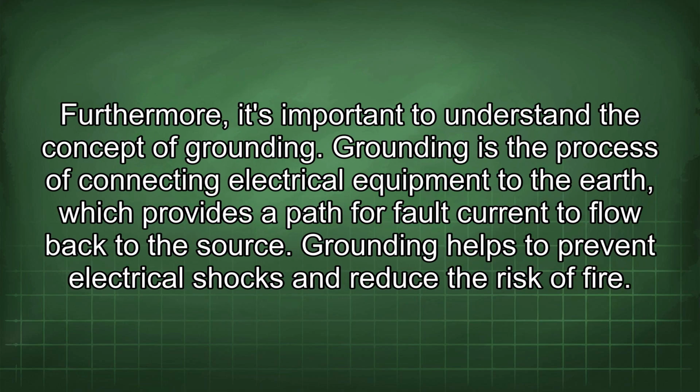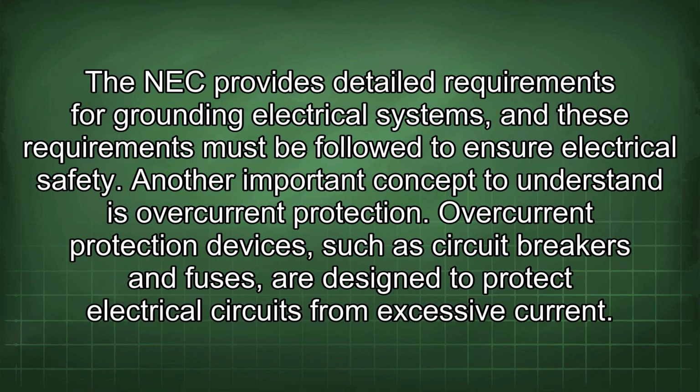Furthermore, it's important to understand the concept of grounding. Grounding is the process of connecting electrical equipment to the earth, which provides a path for fault current to flow back to the source. Grounding helps to prevent electrical shocks and reduce the risk of fire. The NEC provides detailed requirements for grounding electrical systems, and these requirements must be followed to ensure electrical safety.